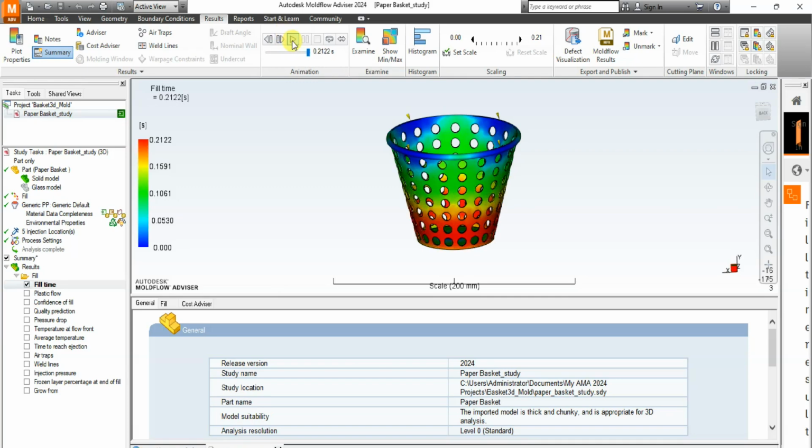Then you also should take note of the contours. The contours should be evenly spaced, and they are also indicators of polymer fill flow. This is very, very important. Another important thing is that the flow pattern is balanced in a part with a good fill time result, which means all 4 parts finish at the same time and reach the edges of the model simultaneously, just like I said previously.